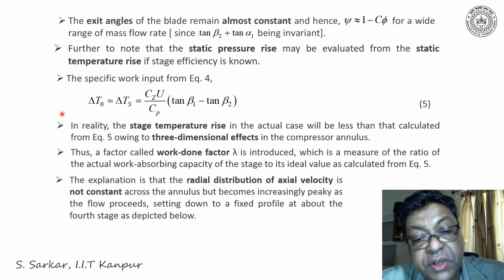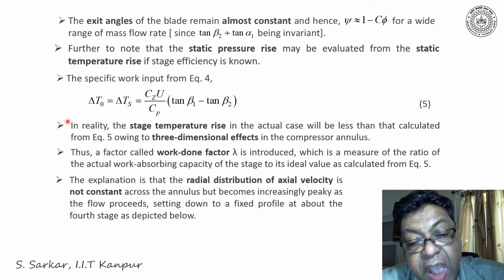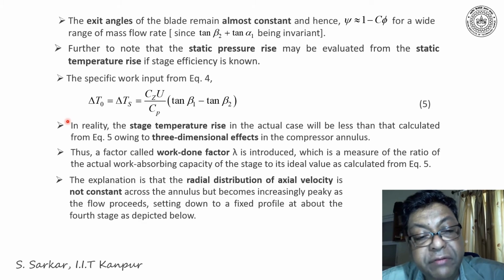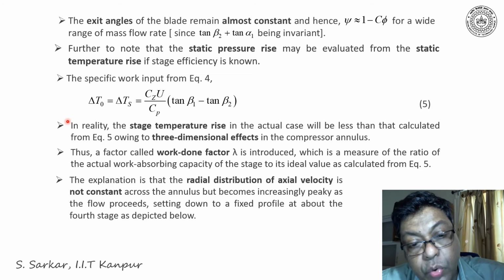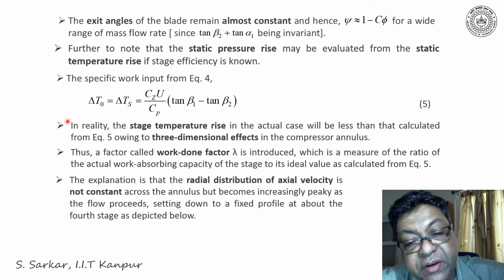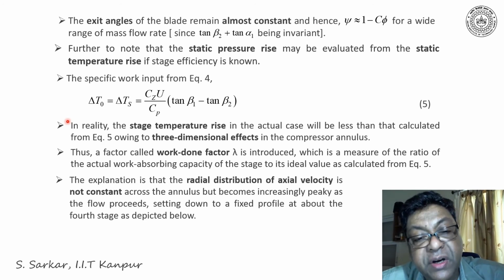However, the stage temperature rise in the actual case will be less than the calculated value from equation 5 owing to the three-dimensional effect in the compressor annulus.